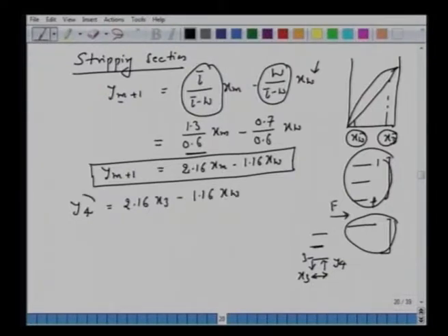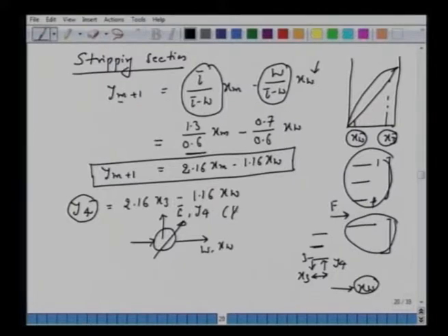Okay, what is Y4? Y4 is in equilibrium with the composition Xw. So when you have the reboiler, the liquid arrives here, we are drawing the product W with Xw, and part of this liquid we are vaporizing as G bar with the composition Y4, or rather Y Np plus 1, where Np is the last stage.